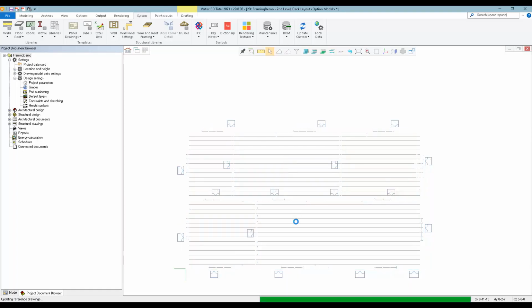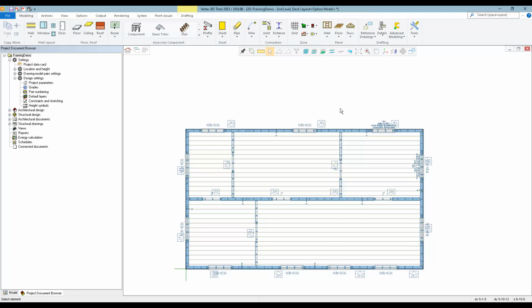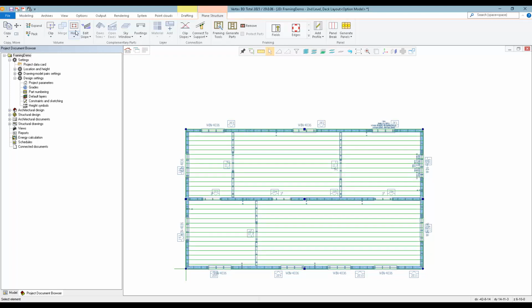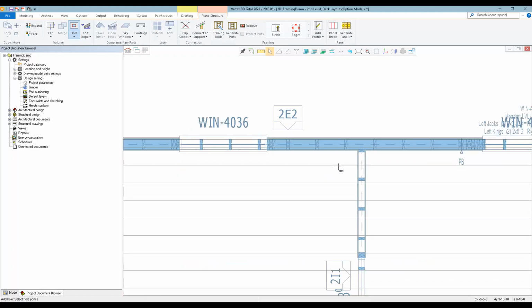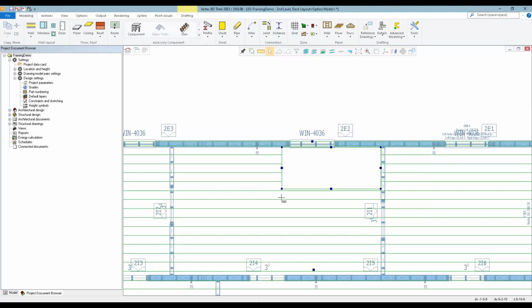I'll switch to the 2D layout, select the floor, so now you can see you have grips and grab points around the perimeter, so you can move the edges or corner points. You can also right click on one and add additional points if needed. I'm also going to use this add hole function, and let's throw in a hole here somewhere, like if we have a stairwell. And you can click multiple points around the hole or just two opposite corners to create a rectangle.